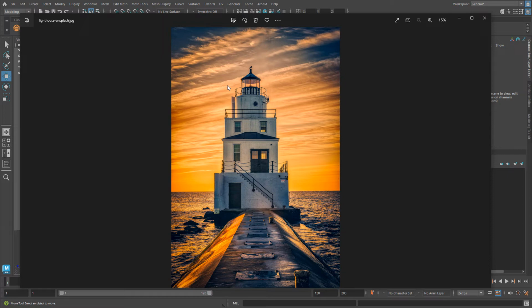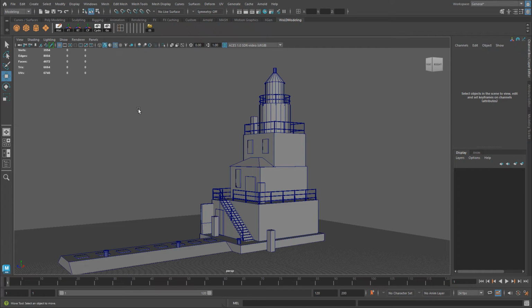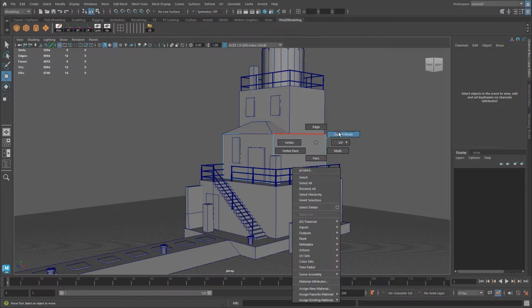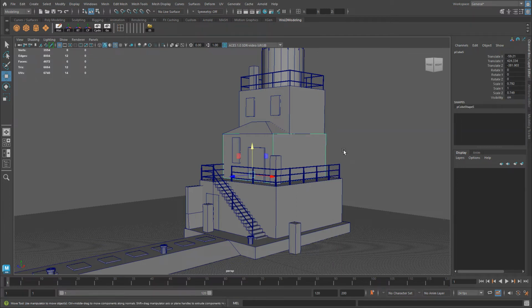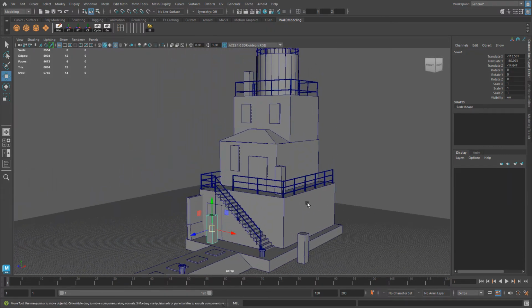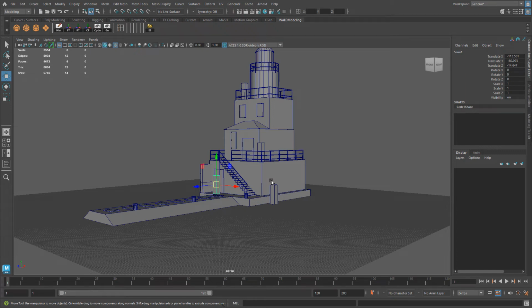So before you start modeling anything and adding those doors, those windows, and actually focusing on the detail of anything in any environment, you need to get the size, the proportion, the scale, the dimensions correct. And you do this by bringing over primitive shapes, changing over to component level, faces, vertices, and edges, moving those edges, moving those vertices, moving those faces, scaling these primitive shapes, inserting a bunch of these human scale references all over your scene so you can judge everything you are blocking out and that it looks correct to the photo reference as well as it matches the human reference scale inside the scene.